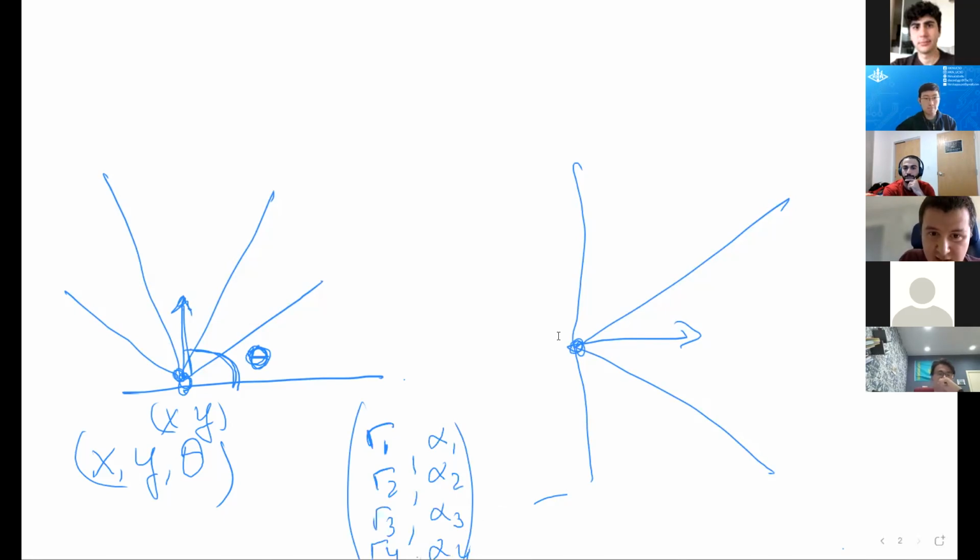And I see more questions here. Does the LiDAR require a robot to have a lot of processing power and memory for the controller? Good question. The LiDAR does not require too much. It has some power requirement, but as long as you have a battery to power it, it will provide this data directly to you. So you don't need too much memory or processing power. The question is, what do we do with these measurements? We'll actually be getting many of them over time, and whether we store them in memory or use them for something is a decision we can make.